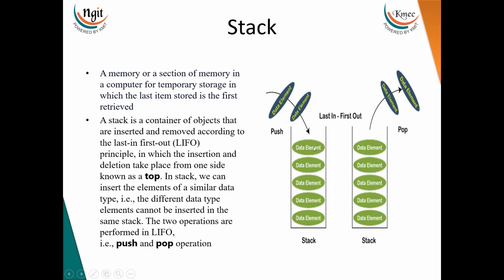If we want to insert data onto the stack, a stack is nothing but a set of memory locations. These memory locations are addressed by one address register called the stack pointer. The stack pointer always holds the top of the stack. Whenever we insert an element, it is inserted onto the top of the stack. Whenever we remove data, the top of the stack is removed first. This is called LIFO, last in first out: the element placed last is taken out first.